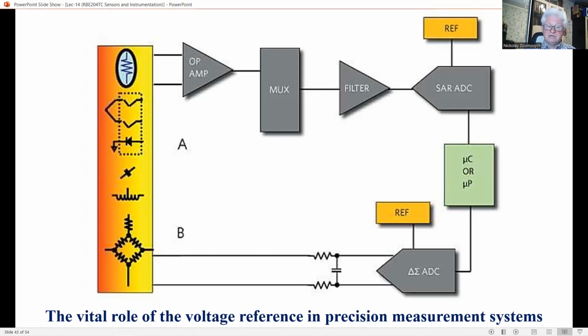However, analog signals have to be preconditioned by using analog circuitry before digitizing in order to eliminate or minimize problems due to aliasing distortion, like high-frequency components above half the sampling frequency appearing as low-frequency components, and leakage, which means error due to the signal truncation, as well as improve the signal level and filter out extraneous noise. The drive system of a plant typically takes in analog signal.